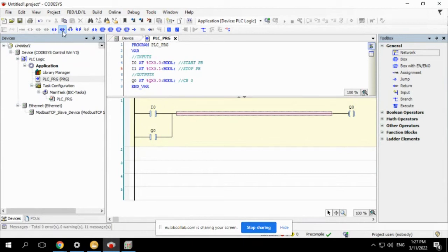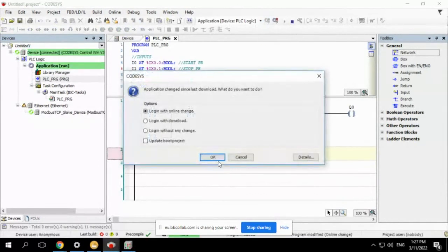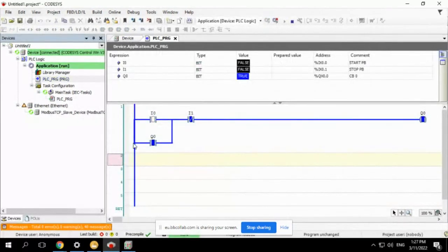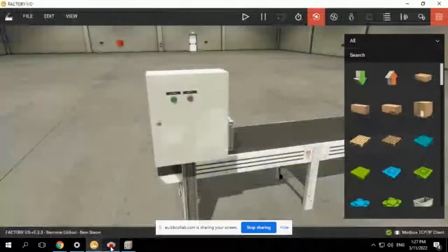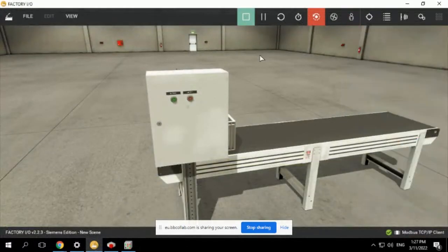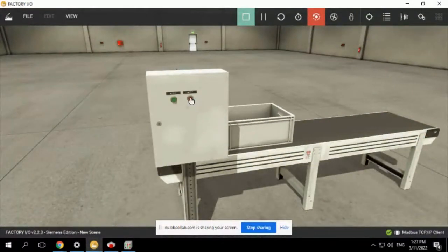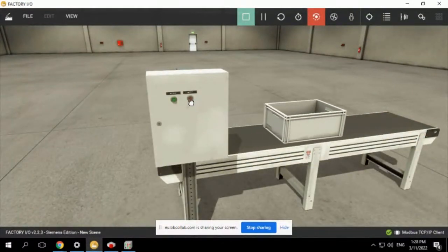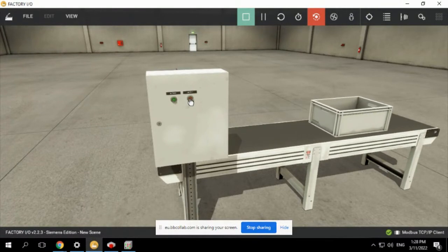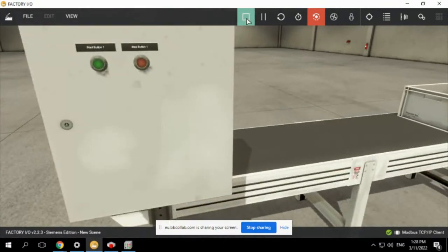Then I'm going to put it as a normally closed at first. I want to teach you something. I1, okay? And you download, immediately download. Okay, so look at something now. When I place this one as I1, automatically the PLC is running. When I press that button, nothing is happening. The PLC continues to run. So it is not responding, all right?